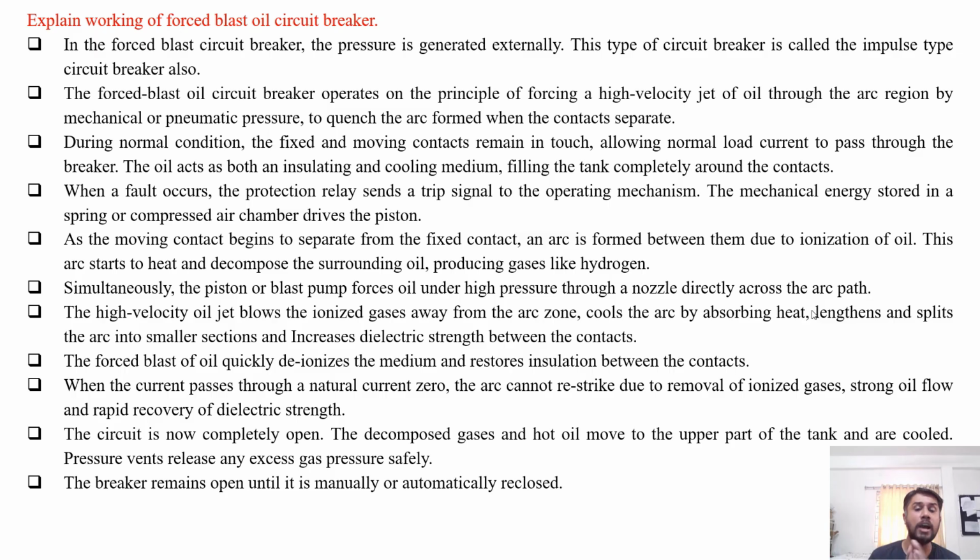The circuit is now completely open. The decomposed gases and hot oil move to the upper part of the tank and are cooled. Pressure vents release any excess gas pressure into the atmosphere safely. Now the breaker remains open until it is manually or automatically reclosed. So this is the simple working of the forced blast oil circuit breaker.